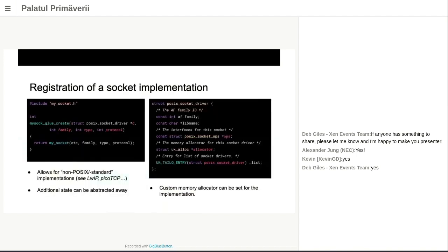With regard to creating an implementation or porting an implementation, such as LWIP, there are also other implementations such as PicoTCP, which was designed with near POSIX compliancy. It is slightly different. Some of the socket function names don't have the same prototype as standard POSIX. But that doesn't mean that you can't use them in a very similar way.